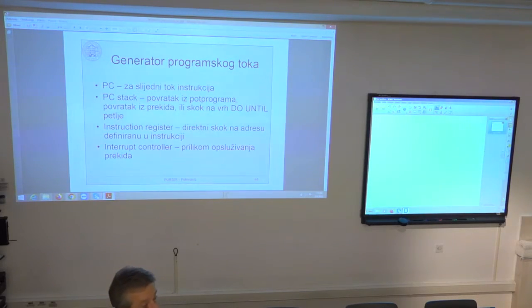And if you have a large overhead, then the efficiency is low, because you have maybe 2 or 3 assembly instructions to do the actual work, arithmetic work, and then you have another 2 or 3 instructions just to control the loop. So it is then a large percentual overhead, and what you want to do is to reduce or to completely eliminate this overhead of program control, to perform, for example, the repeated do loop.